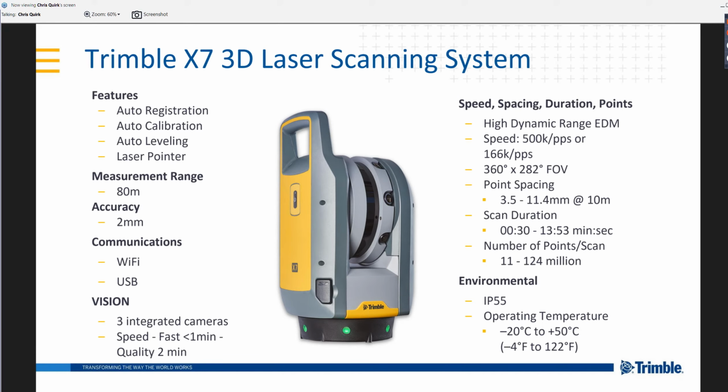And just a recap of some of the specs of the X7. So main features: auto registration, calibration, leveling, and we've got an integrated laser pointer. It's got a range of 80 meters, which we feel is more than sufficient, especially in construction, as you have to move it for line of sight. Accuracy of 2 millimeters. It communicates with the tablet via Wi-Fi, but we do have a USB port as well. It may be that you might be out on a site, maybe an MOD site, where you can't have Wi-Fi. You can still use the scanner and use a USB to transfer the data.